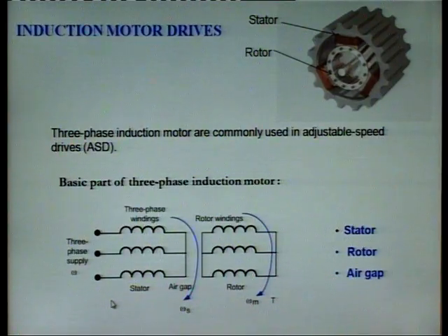If the number of poles is 2, it becomes a synchronous speed of 3000 rpm. So, the stator rotating field is rotating at a speed of 3000 rpm. The rotor magnetic field is also trying to rotate because of mutual induction, but if these speeds are the same,